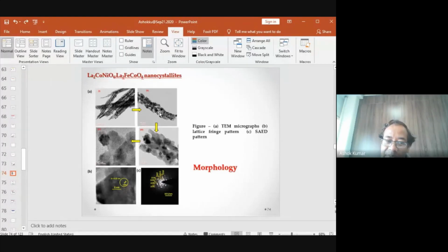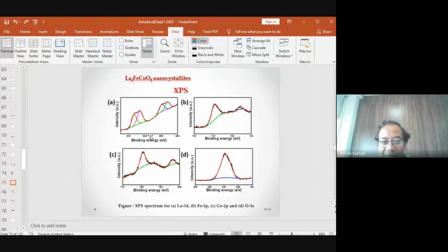And the pore should not be a very high area. It should be smaller. For this particular application it should be in the mesoporous size, that means 2 to 50 nanometer. That range should not be higher. So that provides very good morphology. If you target this particular application, then rod-like morphology with pores is considered ideal morphology. And you can see here with the zoom view, you have particles here. You can see clearly, and we were able to synthesize these particles. So this is the nanostructured material we are talking about.